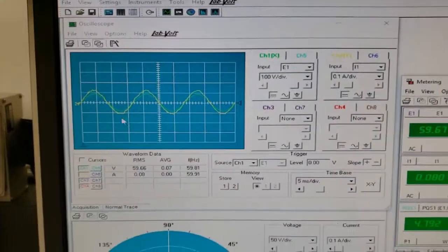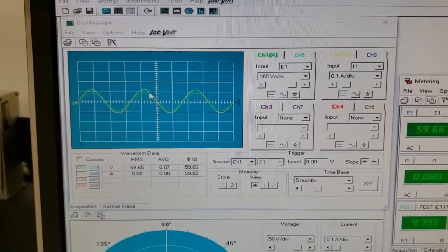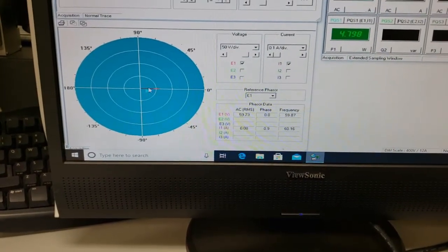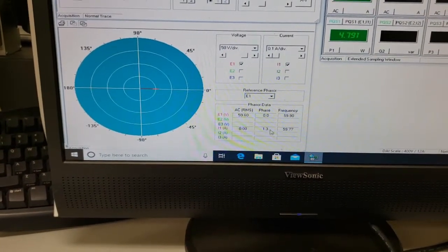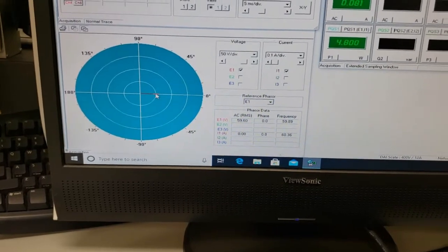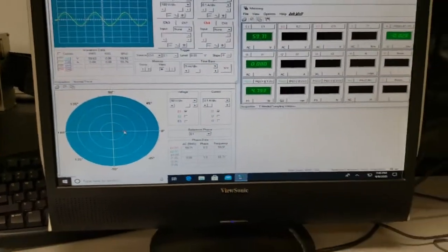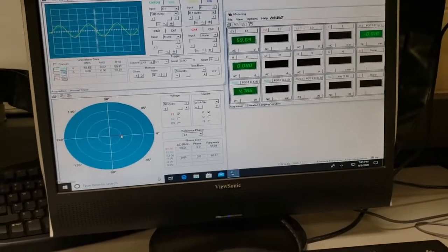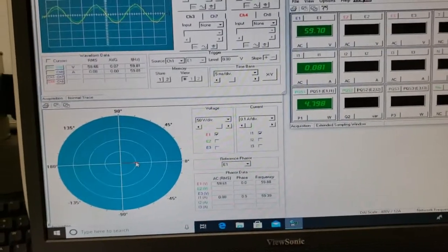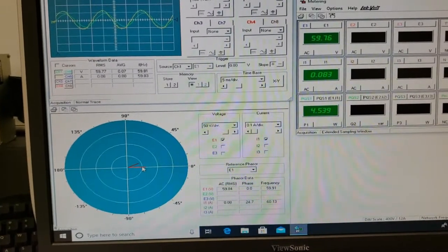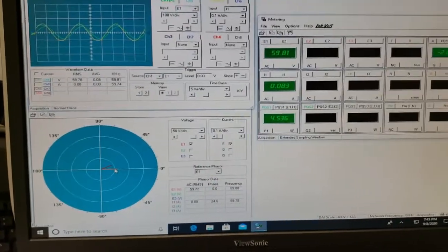And look over here, the voltage and current waveforms are pretty much in phase. And you can also see that almost exactly in phase, just 0.9, 1.3 degrees off from each other, but that's almost exact. So that's very nice. In fact, I can show you dynamically what happens if I switch everything off, the corrective load off. There, they become offset. If I switch it back on to correct the power factor, let me also show there.